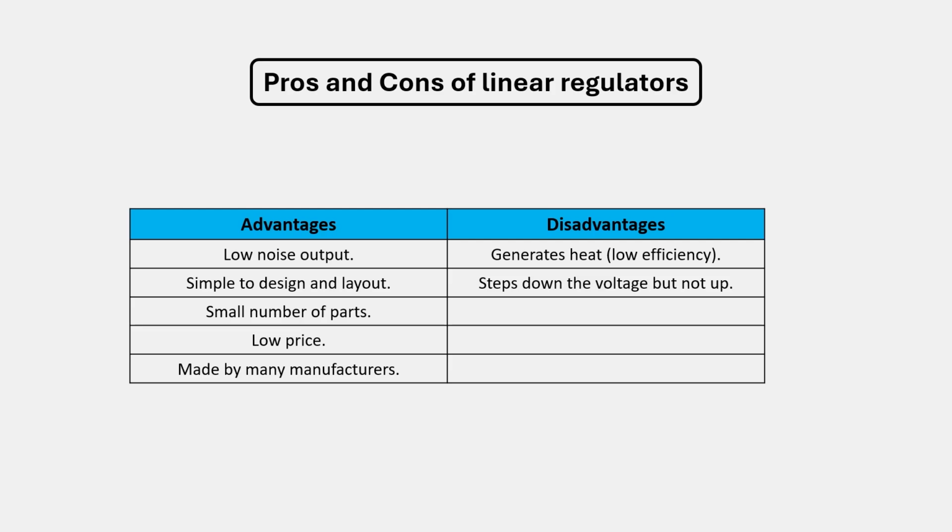So to sum it up, use it for sensitive applications in terms of noise, such as analog to digital converters and stuff like that, audio circuits, if you need some nice audio quality. And make sure that the heat aspect of the design is very well designed and very well calculated. And besides that, do not use it for high power applications, as we now have switching regulators that can deliver really nice results and deliver quality output in terms of noise.